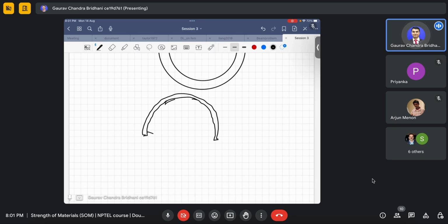So he said that because of this internal pressure, the pressure is acting something like this. So what will happen? This pressure will give you a reaction, something like this at the ends if you cut. The resultant of all this pressure will give you some resultant force in the vertical direction. But you can see that these arrows which I am drawing are actually perpendicular to the surface. Wherever I draw, suppose here, I will draw a tangent and it should be perpendicular.